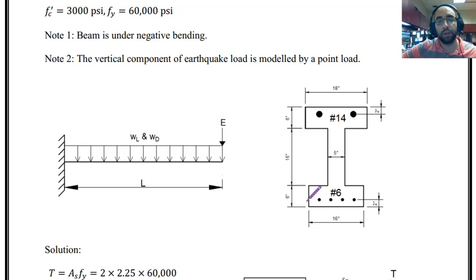And see the maximum earthquake load. One thing that is good to notice and also mention when you are working outside, in consultant companies, is that usually they don't include compression reinforcement in a strength analysis. They just ignore it and find the strength of the section based on tensile reinforcement. It will simplify the procedure.